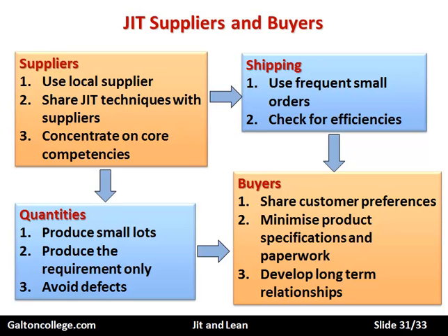And the quantities, well, produce small lots. Always try to produce small quantities if possible. Large quantities will require holding stocks waiting to be processed. That's a waste. And large stocks will have to be dealt with at the end, and sometimes the items going to dispatch will be held in dispatch for some time, because it takes dispatch some time to organize complete deliveries if it's a large order. So small deliveries, part orders delivered, might be the way forward. So check if that's possible.